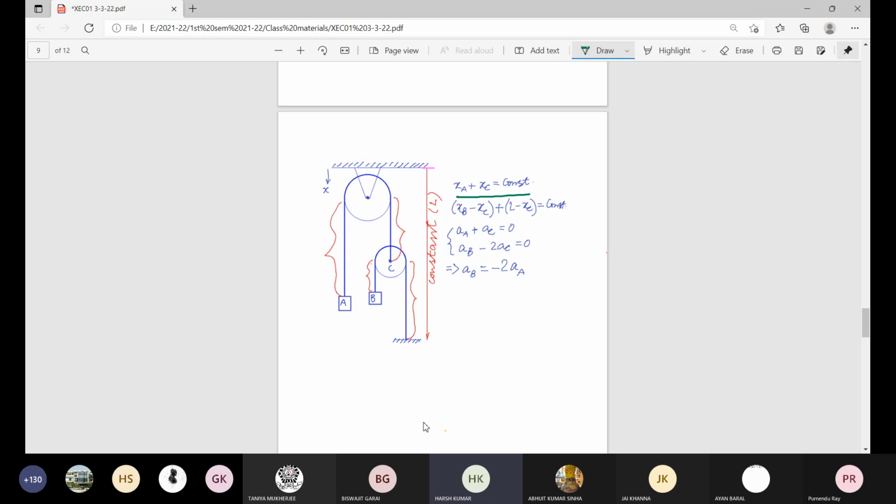No, sir. I'm asking about a method where the velocity of the pulley is equal to the summation of the individual strings' velocities divided by 2. Where do you get that shortcut relation from? Sir, from here only: deriving that the total length is equal to constant, and then differentiating. The starting point should be this one at least.